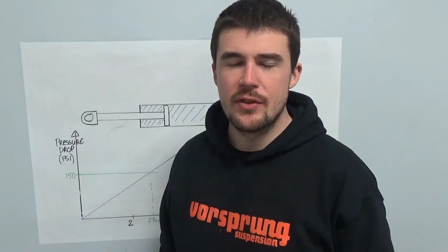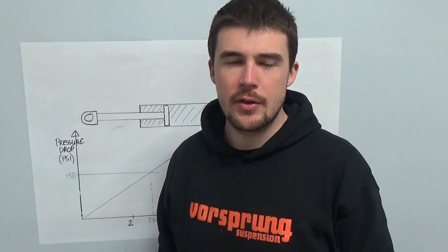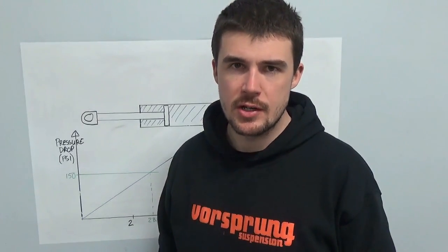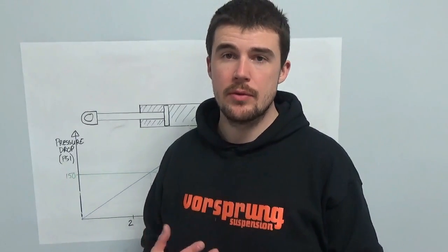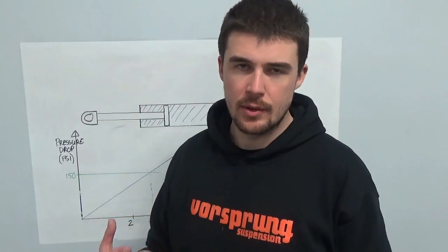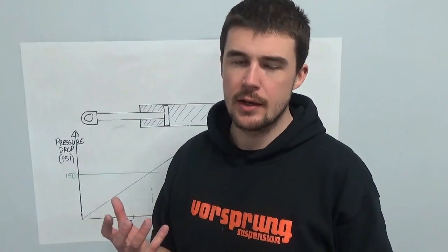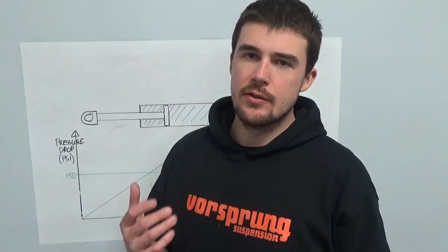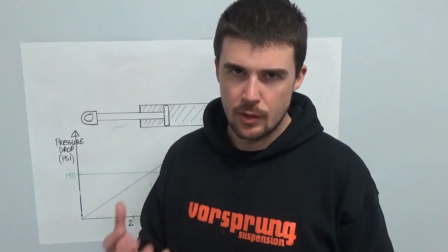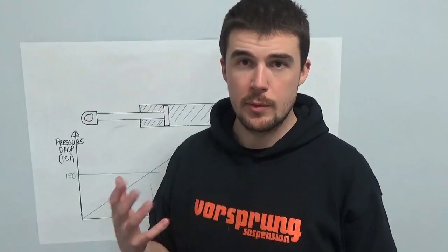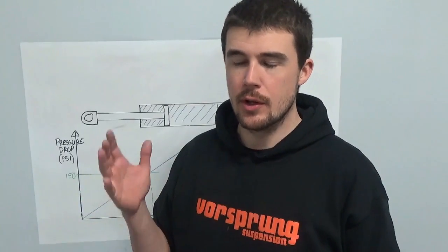The third common misconception that we hear is basically misuse of the term cavitation. So we'll commonly hear people say something is cavitated, or they have cavitated oil or something like that. Cavitation is not foamy oil. It's not air in your oil. That's aerated oil or foamy oil or air in your oil, or whatever you want to call it.